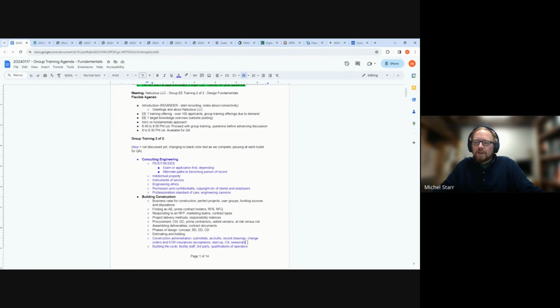There's training involved, commissioning. So the commissioning being after you said, okay, it's done, then going in there and making sure it's performing functionally. And then, even from the basic installations, it's a checking of the installation and of the product, because that's what buildings are. They're very big, expensive products. And then seasonally should be coming back. If you're testing in the winter versus the summer, there's 6 months come back.